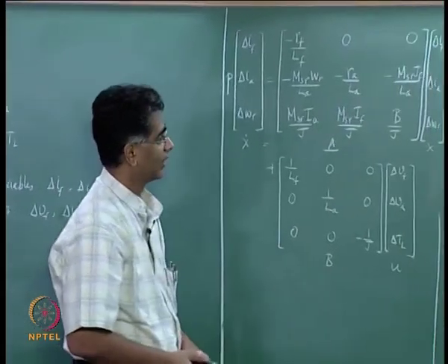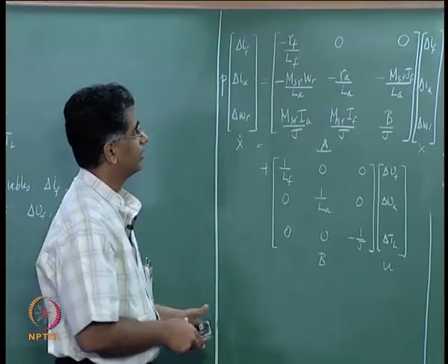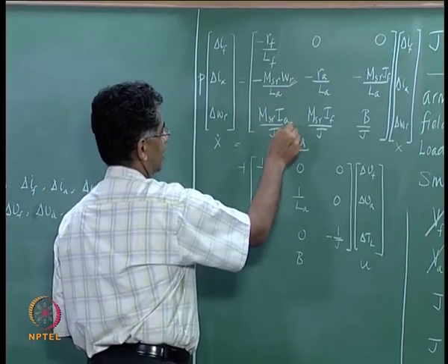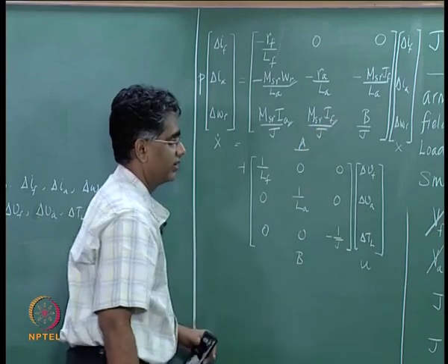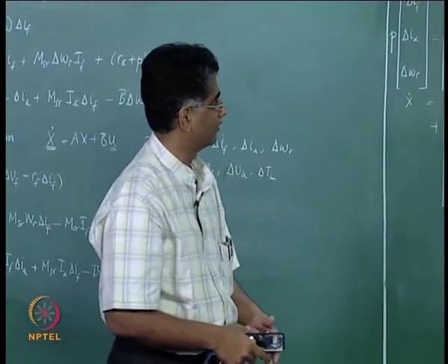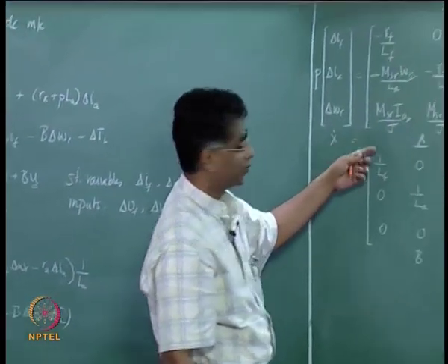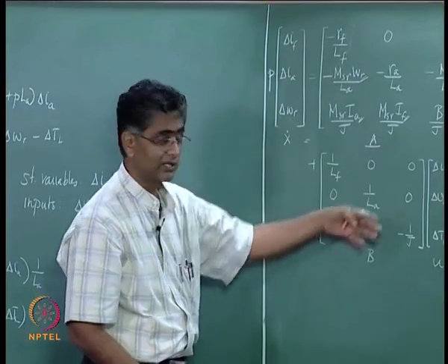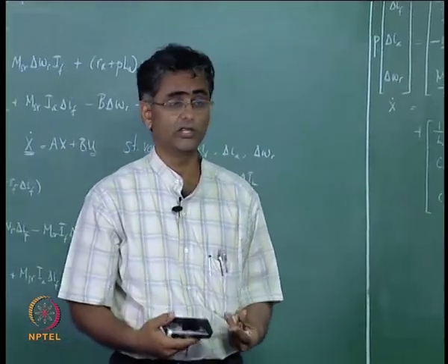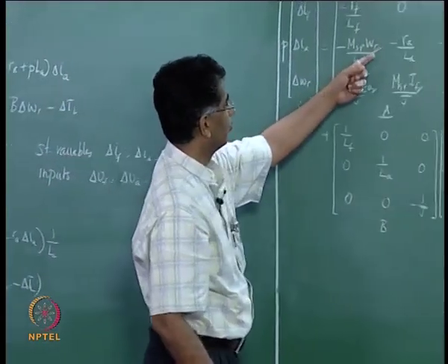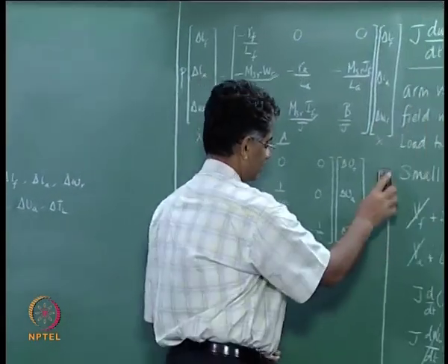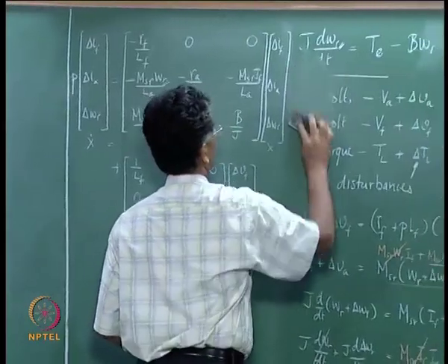But note that this model is going to depend upon values that you plug in for omega r, capital IA and capital IF. That means as the steady state is going to change with different amounts of loading, the response to disturbances, which is represented by this system of equations, can also change because it depends upon where the steady state is. But nevertheless, this is a useful tool in order to study the responses.